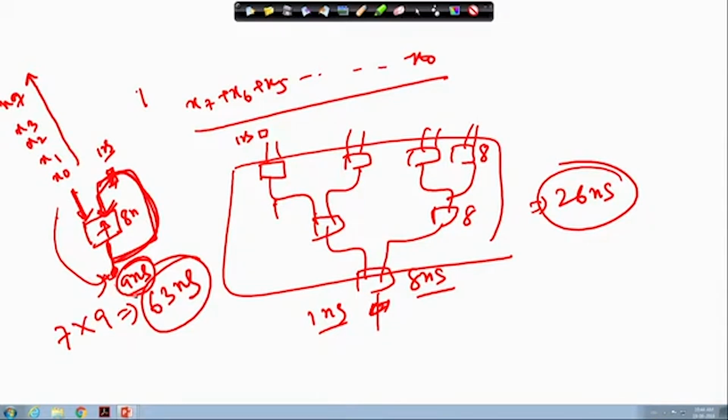Okay. So, that is why here, what is the number over here which I require? That is 20 nanosecond. But what is the number here I require? That is 63 nanosecond. Okay. So, that is why here, though I can reduce the corresponding hardware, for each of the samples to be computed I require more time to wait than this particular parallel implementation. Okay. So, this is the advantage.